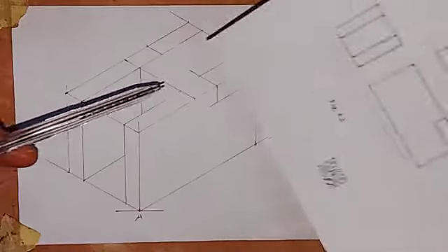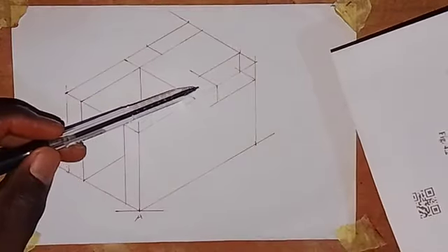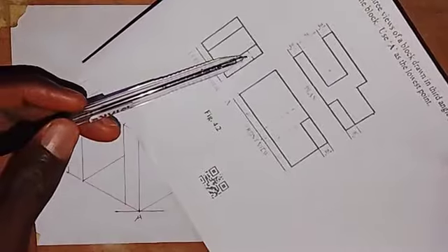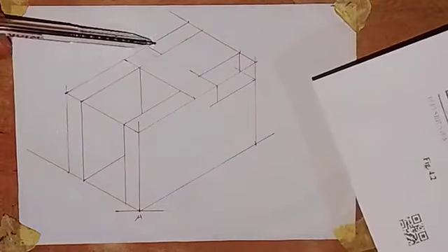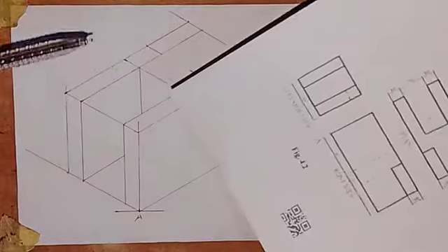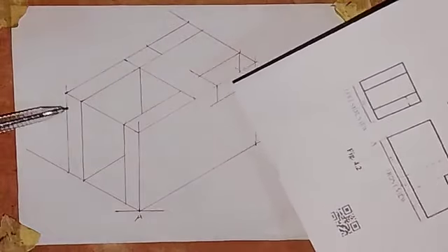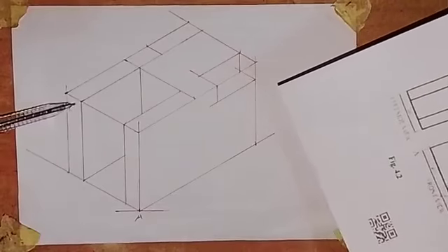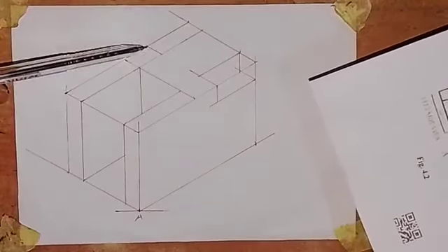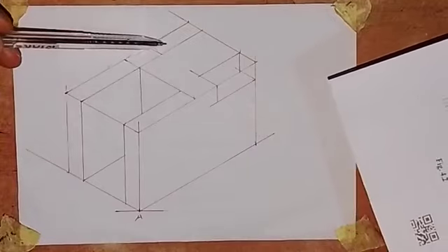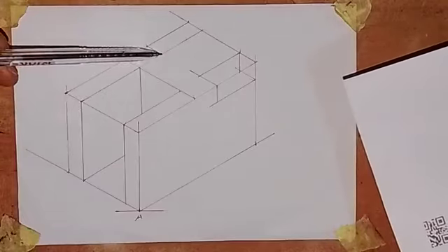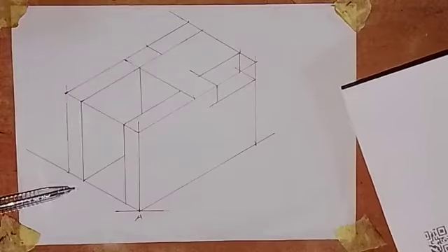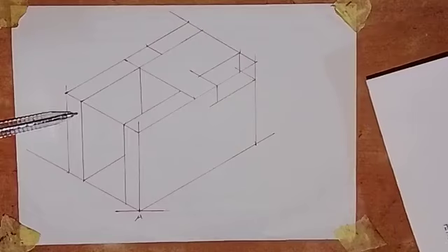So this part that is cut, the line at this point that goes inward, is what we see here that is hidden. And at this point down, we have a rectangle, and this rectangle is this. If you look at it, the thickness from here to here is 10, from here to here is also 10. So this rectangle that we have here, we also have it here. So we are not showing the line that we have here that is hidden, because this line has prevail over it.